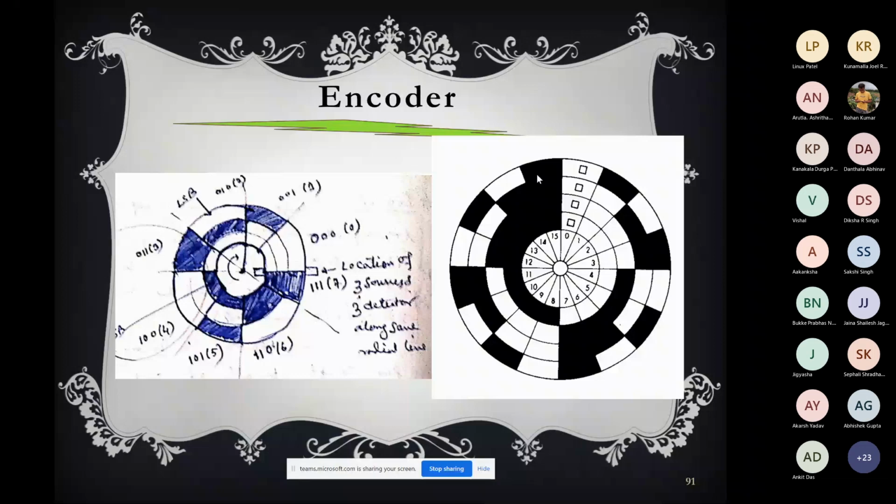So we'll get an output that is a kind of sinusoidal output. You may think it will be square, but it will never be square, because there will be no such perfect transition. Whatever focusing you do, the light will disperse a little bit, and the voltage at the detector will slowly rise and then fall. So you have a kind of sinusoidal output with theta.